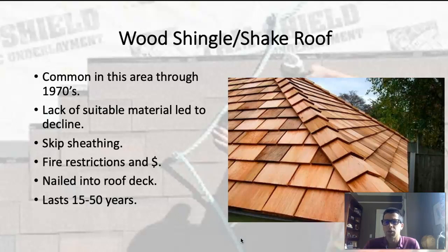Whereas the shingles, for the most part, are going to be pretty consistent in thickness. And they're going to be tapered. They're going to be 5/16, 3/8 or something at the butt. The thick part is called the butt. And then they're going to taper down essentially to a feathered edge at the back.